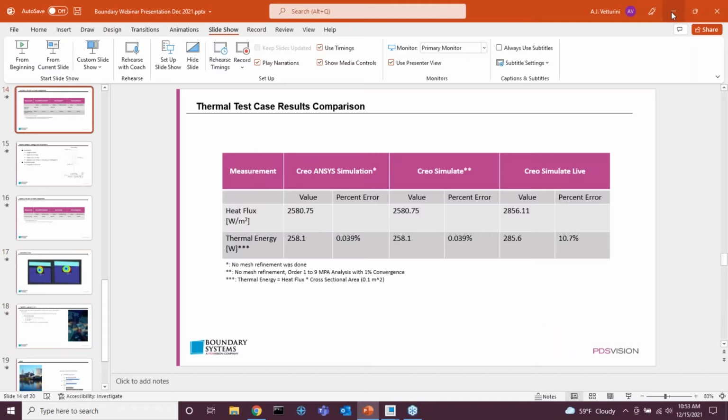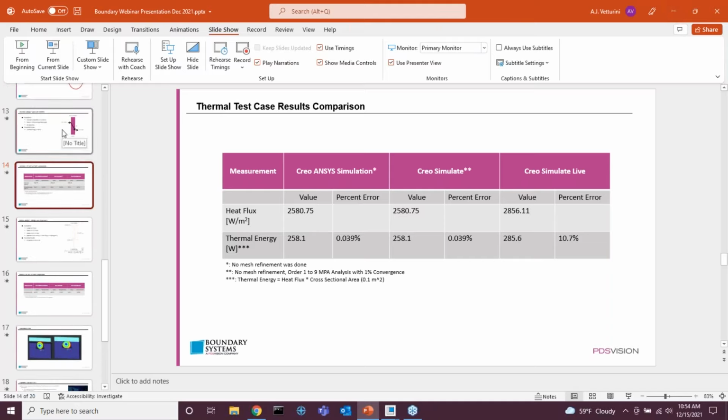The only differences you might see is that in ANSYS Mechanical, you do have the full tools available to your use. So if you change anything inside of ANSYS Mechanical, add new loads, add whatever, that would obviously cause a difference. But in terms of apples to apples, Creo ANSYS Simulation to ANSYS Mechanical, as long as ANSYS Mechanical is using the same version solver as you, which in Creo 8, again, is 2021 R1, there would not be any difference between the two.